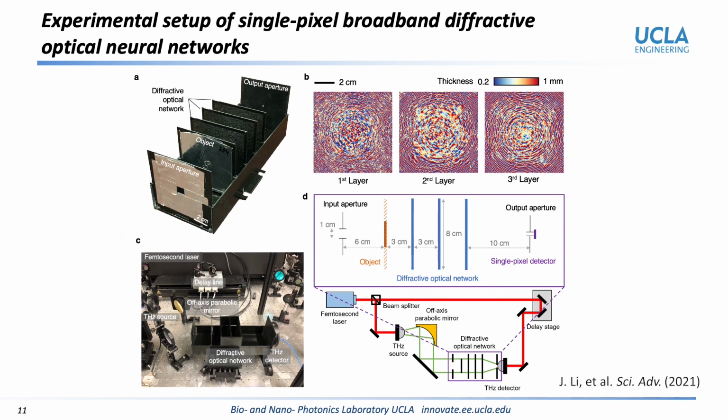We demonstrated the success of this machine vision framework through a set of trained diffractive networks that are composed of 3 layers. After 3D printing of these resulting diffractive layers, we experimentally validated the success of these single pixel image classification systems by classifying handwritten digits at the terahertz band, using a snapshot broadband illumination and a plasmonic nanoantenna-based spectroscopic detector.